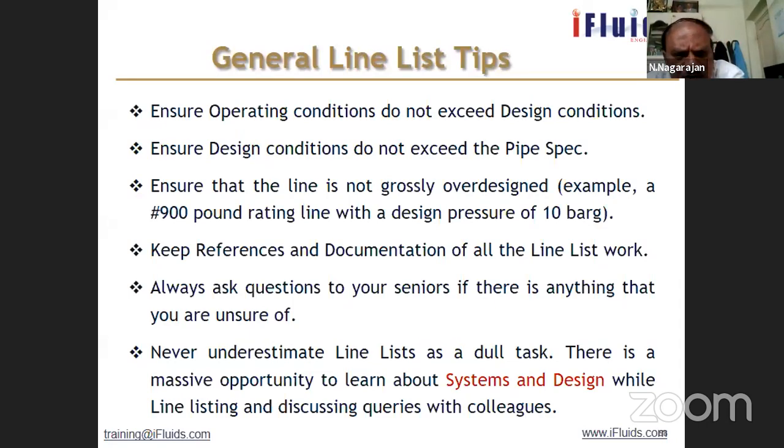Ensure that you don't grossly oversize the pipes. With a design pressure of 10 bar gauge, you should not put a 900 pound rating. 10 bar gauge is coming within the 150 pound rating. Like that, you have to see these anomalies.